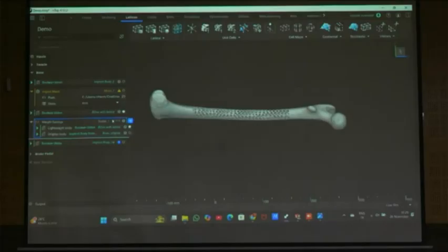And the constraint is that it should not exceed this much, it should not remove this material: passive region, non-passive region, like the design space, non-design space, and it should not exceed this much stress. These are the constraints actually. According to that, it will generate the design or optimize the body, that we call topology optimization. The algorithms are different for both things.